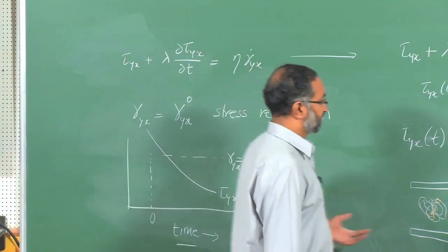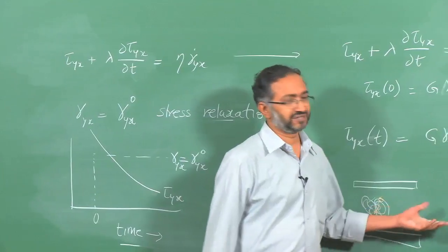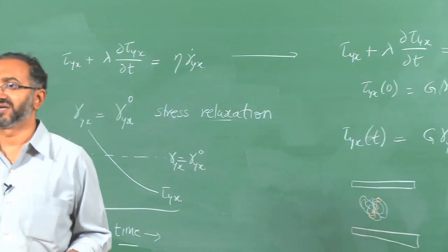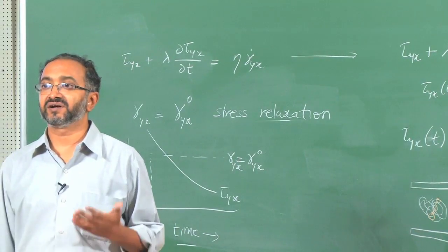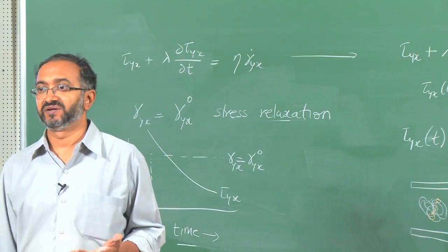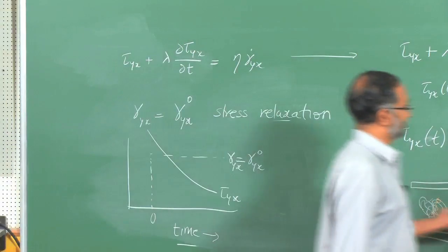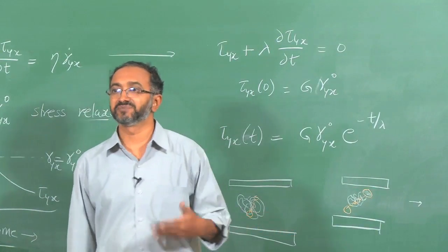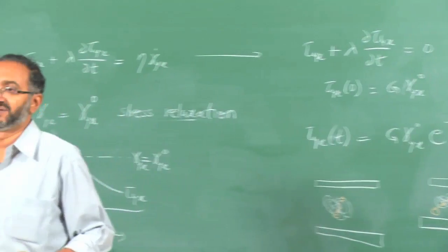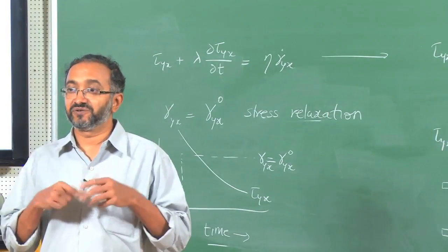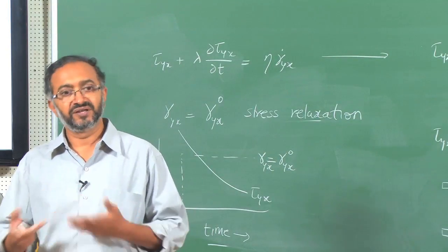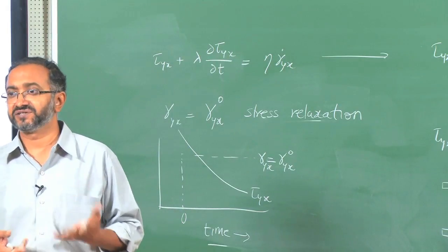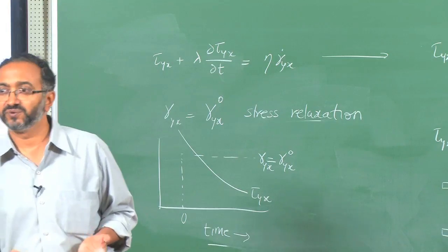Yeah, no, so compressible and non-compressible fluids as far as viscous flow and dissipation is concerned are similar. In that case the only thing is the pressure is also another variable. In our case we are never discussing pressure, so I am only saying temperature will be different in two cases, right, but in compressible flow pressure is also another variable. But from a molecular standpoint, from the point of view of relaxation processes, incompressible and compressible fluids will have similar features. They will have viscous response only, dissipative response only.